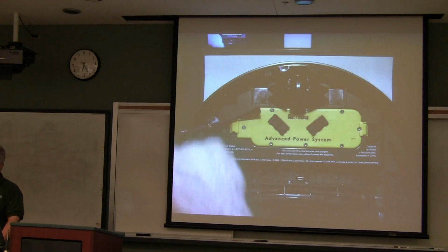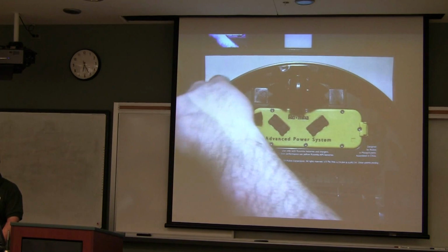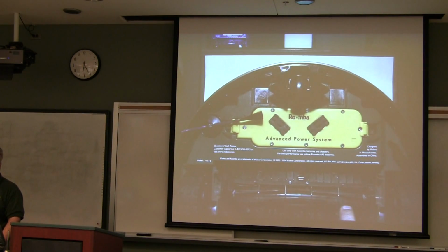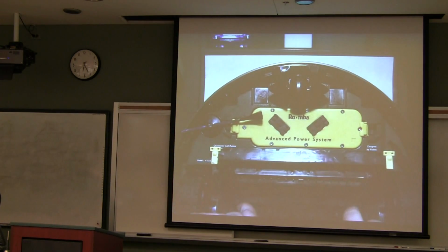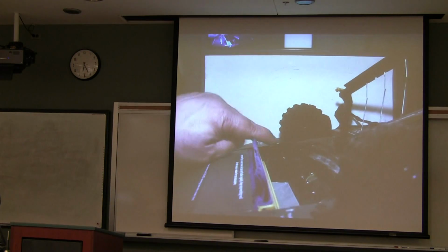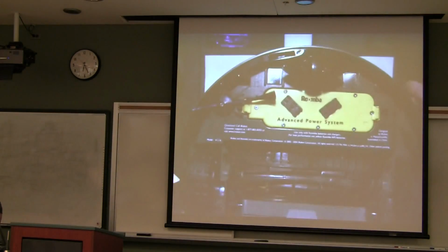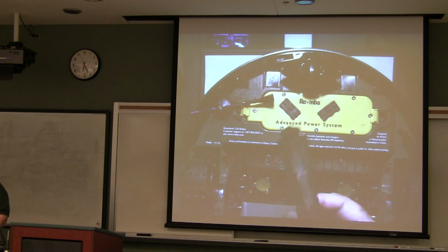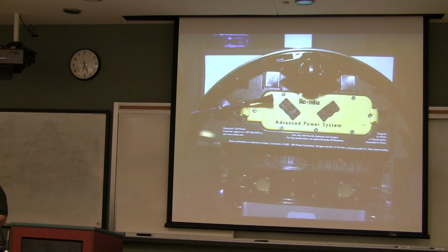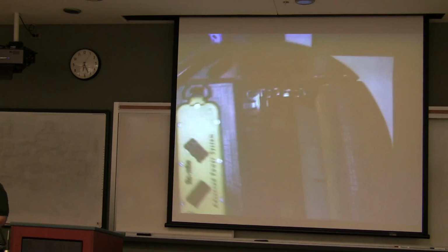This is a cute little thing. When it's running, it goes along and sweeps stuff, and I think it rotates in this direction, so it sweeps stuff underneath so that it'll be sucked up by the vacuum. What you have here are brushes, and there are motors here as well. You can't see that part. So right here are motor drives as well, to be able to turn the brushes. There's two different ones. There's this brush, which is rubber, and this brush, which has bristles like you typically see. And they sweep the dirt into this cavity under here.